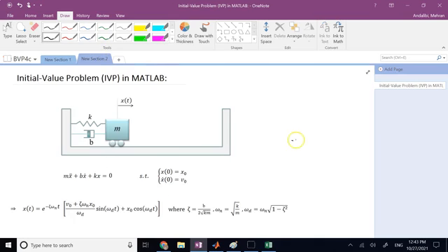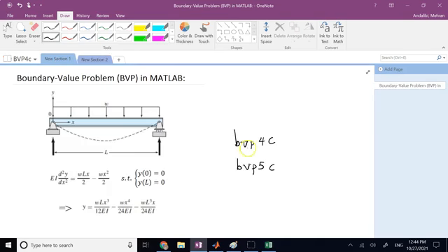And in this one, as I said, we are going to use ode45 most of the time, unless the differential equation is what we call stiff. Then we use some other solvers, like ode15s and so on. So both of these solvers, I'm going to use bvp4c, can only solve first order differential equations. They cannot solve higher order differential equations. They can solve several first order ODEs at the same time, but nothing that you pass to them can be more than first order.